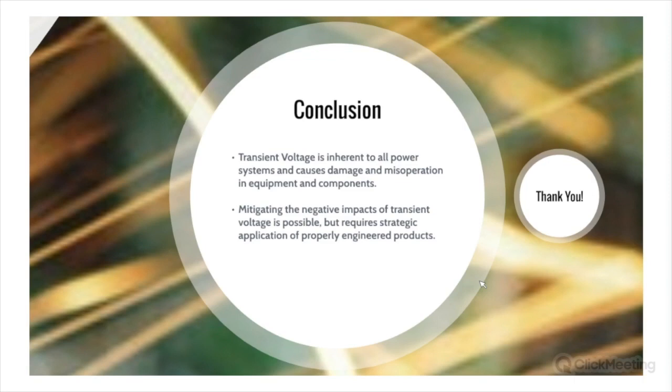And I assume that's why a lot of y'all are on today. And we know that step 1 of the process, of course, is be aware you have a challenge. Step 2 is select a transient voltage surge suppressor that can turn on within the immunity level of the equipment.